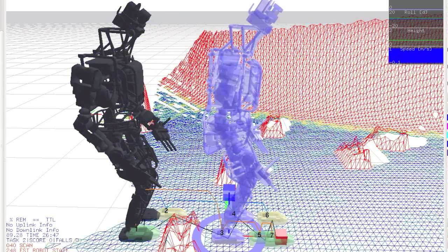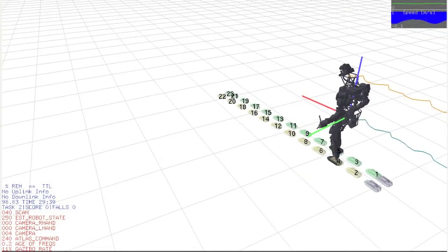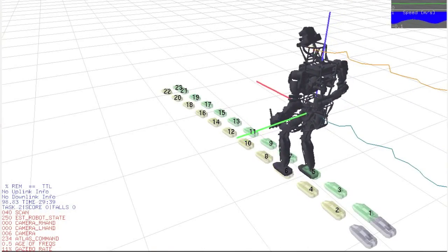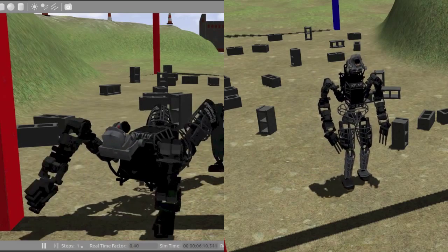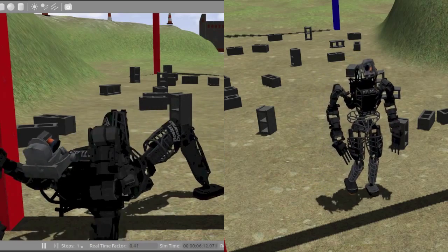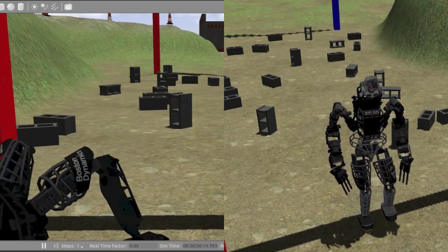Due to the low drift rate of our state estimator, continuous LiDAR fusion allowed our controller to also modify its foot placement while in motion. When walking failed due to collisions or unstable interaction with the terrain, a series of recovery motions allowed the operator to direct the robot back to standing or into our dynamic quadrupedal crawling gait.